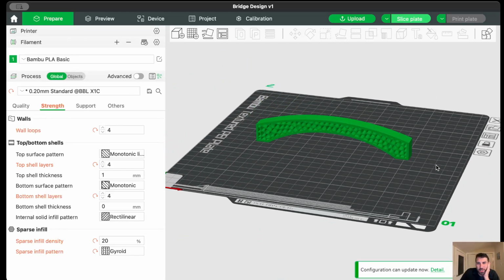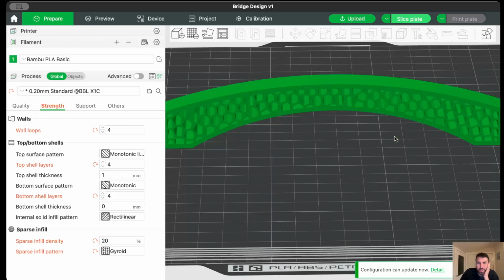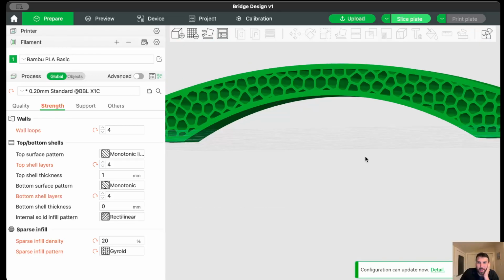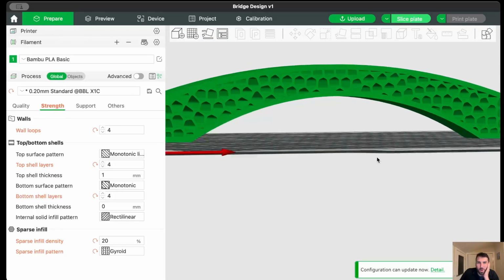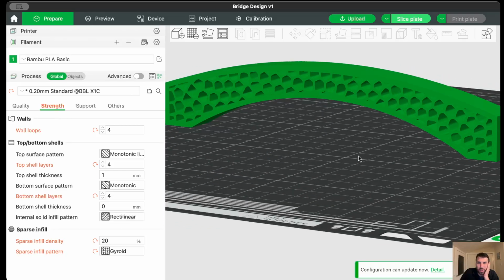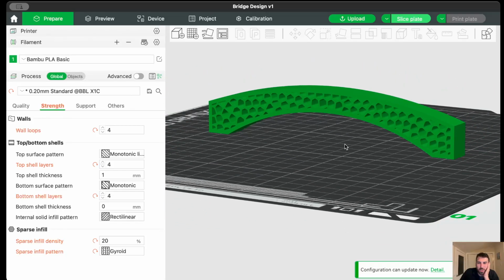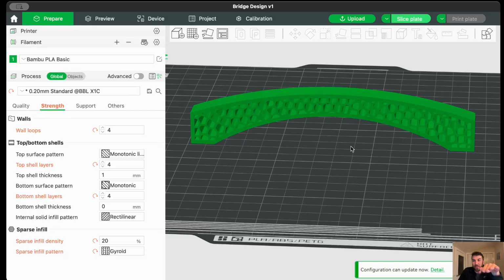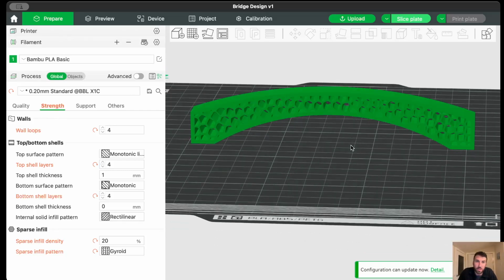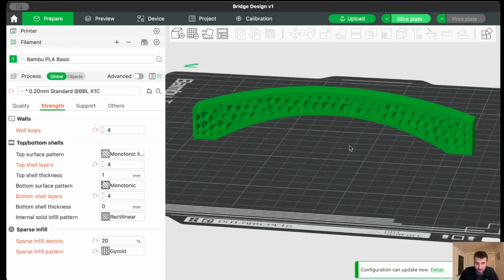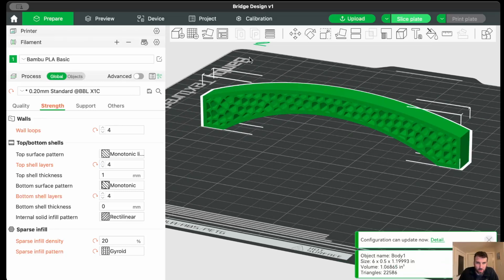Now, this is not necessarily the best orientation to print it because it will likely need supports on the bottom. It may work, but this is just a harder way to do it. Another way to do it is if you flipped it and printed it with the side on the bottom, it would be a little easier. To do that, I just want to show you that you can edit this in Bambu, which is often nice to do for these kinds of final edits in your slicer, whatever you're using. If you're doing 3D printing, it makes it a little easier.